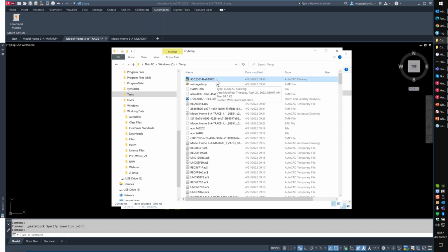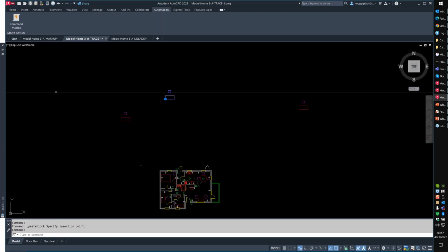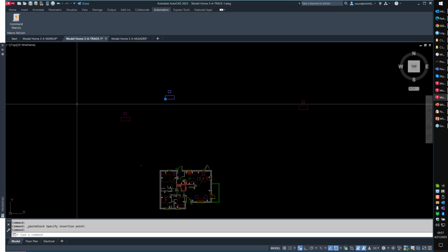And that gets inserted as if you were to have right blocked out the information using WB, called it this name, stuck it in your temp folder, and then just pasted and inserted the block using the block insert command from here. Mike, I hope that answered your question in a long roundabout way.